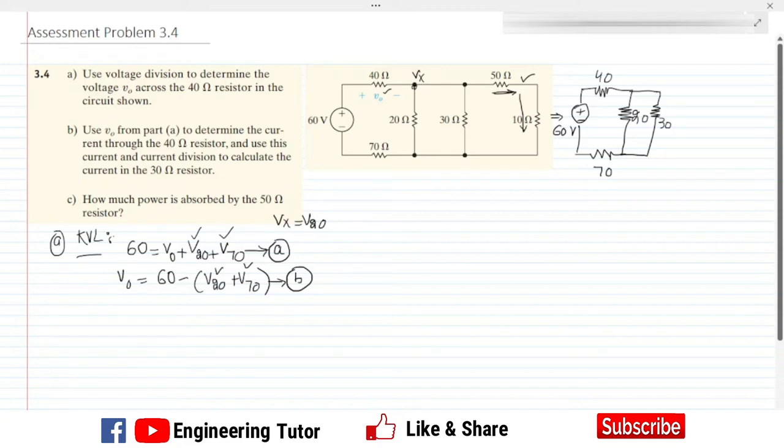So we will start converting the circuit from the back end. When we convert it, by adding them together, because two resistors are in series, we will get a 60 ohm resistor. So this is the first equivalent circuit. After it, we can see that the voltage Vx will remain the same here, here, and here. These three are in parallel. So in order to find the equivalent circuit again, we are simplifying our circuit. So this is the circuit.